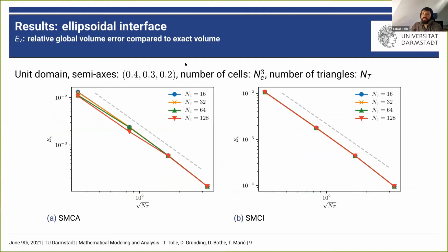For example, here, this ellipsoid case takes about 20 seconds with the finest resolution. But I guess if you would take real-world geometries, there is always a danger that something still goes wrong in these geometrical operations. This will then introduce spurious volume fractions, so that you maybe get small satellite drops close to your surface, which will cause problems in the simulation.